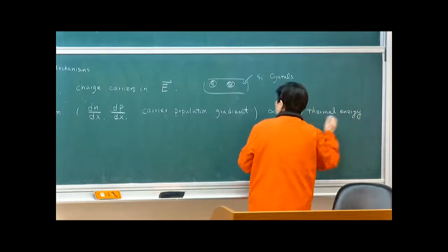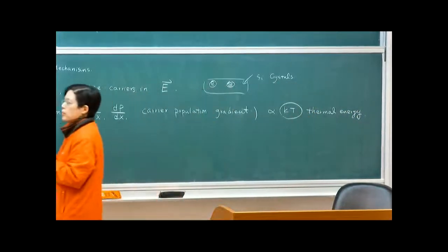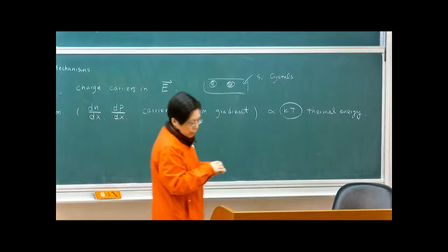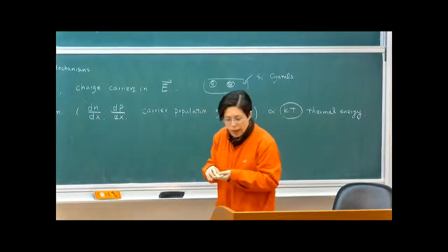Think about it, if you go to the South Pole or somewhere very cold, it's not very effective to wear perfume because it will not travel too far, because the diffusion is limited by the amount of thermal forces driving it. We're going to look at diffusion a little bit. So you can think about the underlying energy source. One is from the electric field. The other is actually from thermal energy in the system. So let's first look at drift current.